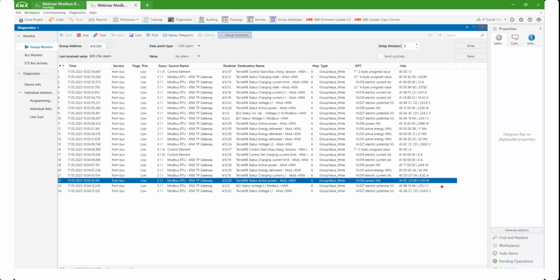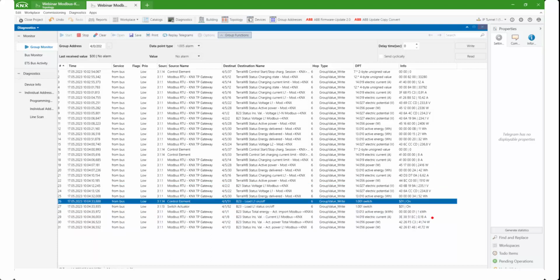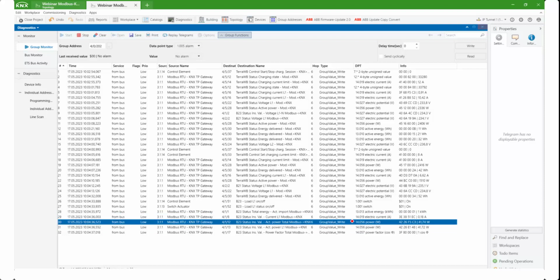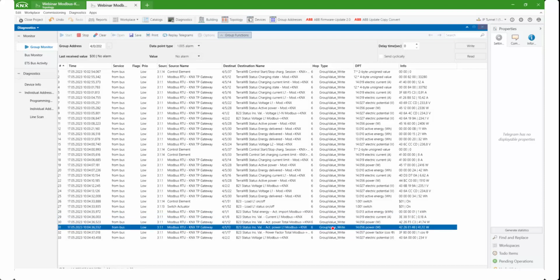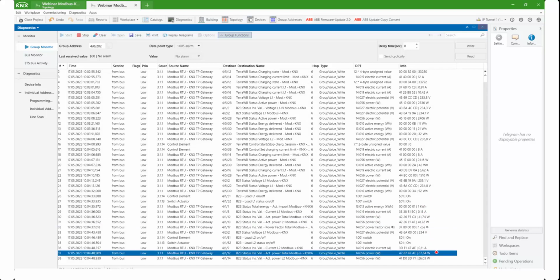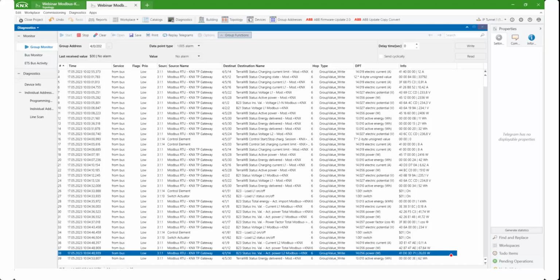Good. Or for example, I switch on here my B21 meter via KNX telegram, and then you will see here the current of my B23 meter. I see here then the power, the total power, the power per phase L1. And when I switch on here another device, another channel, my phase L2, then you see here 67 total, and here 26 of my phase L2.